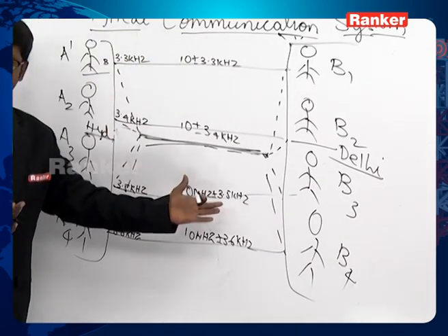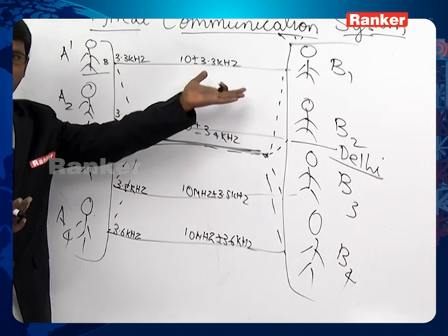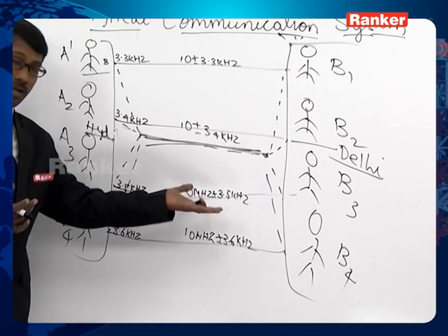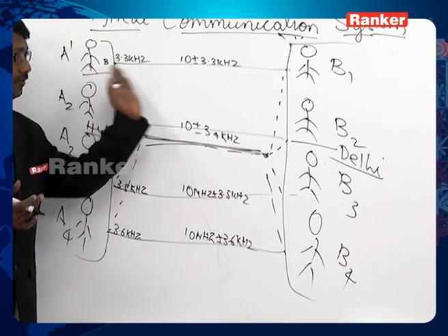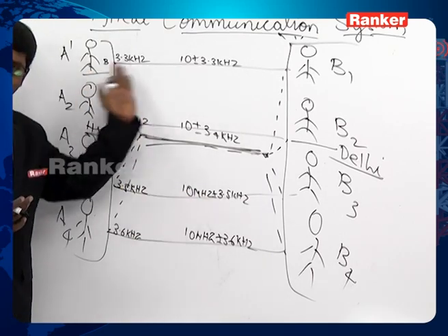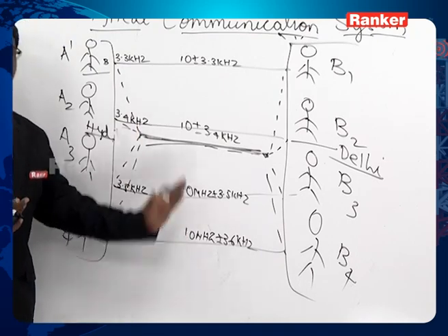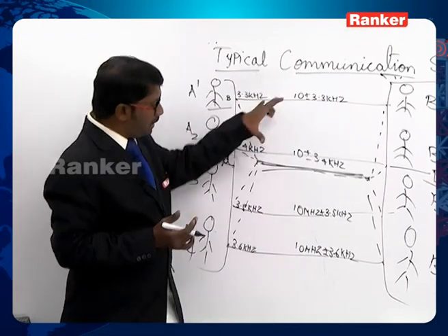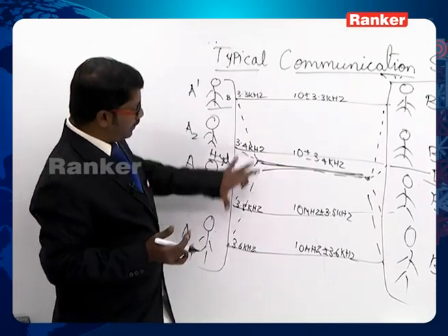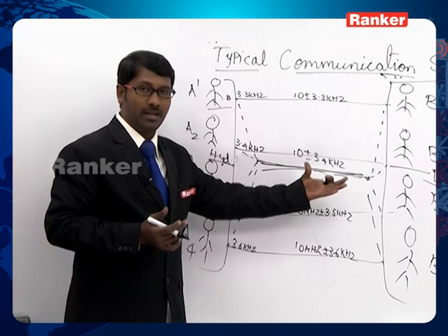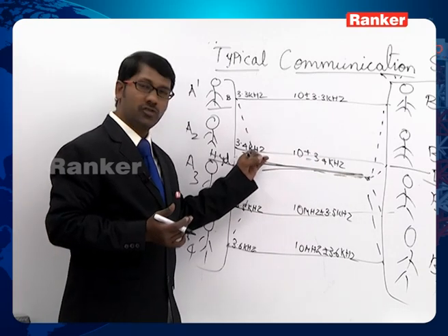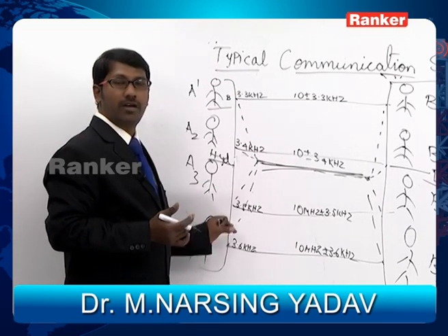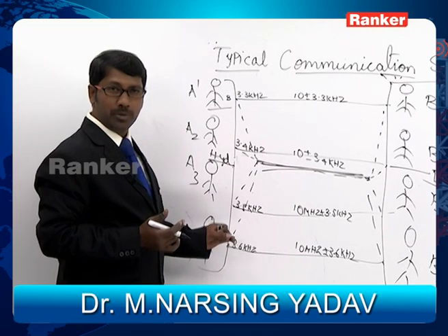line like this, say for example, this has to be given at 10 kilohertz, this has to be given at 20 kilohertz, this has to be given at 30 kilohertz, this has to be given at 40 kilohertz. If I give individual frequencies, individual high carrier frequencies to these, then this is wasting my bandwidth. So multiplexing has brought 4 different signals onto a single channel, and it is doing the job of conserving your bandwidth and also avoiding interference from multiple users.